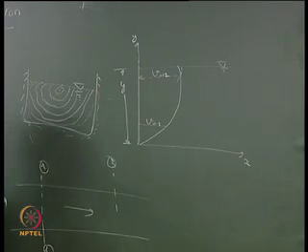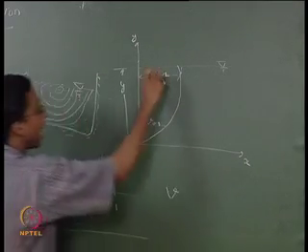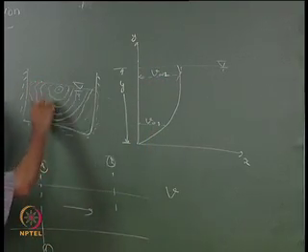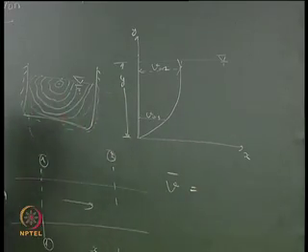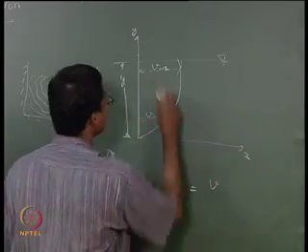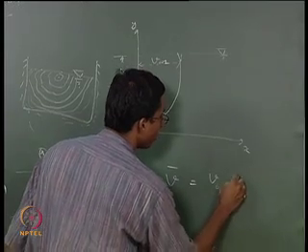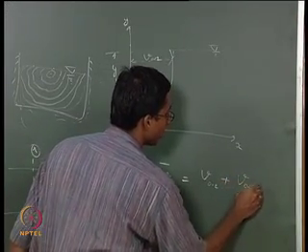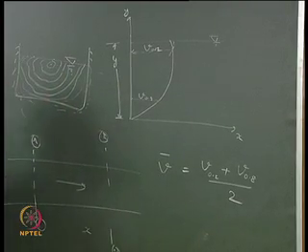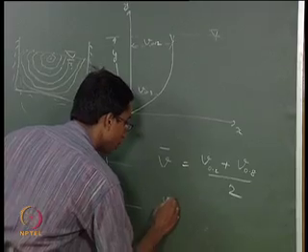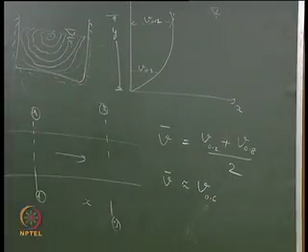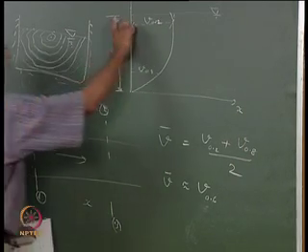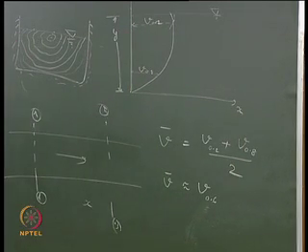Some of the experimental studies have also suggested that the average velocity in this cross section can be given as the velocity obtained at 0.2 plus the velocity obtained at 0.8, divided by 2, or it is more often suggested that the average velocity is the velocity at 0.6 depth of the flow.